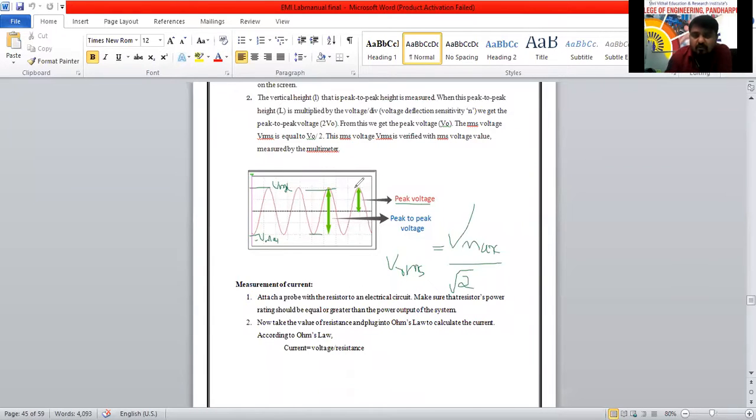That is the AC voltage it is going to give, and this is the peak to peak value we are going to measure here, and the peak value and the time period. Time period is very important. If we know the value of resistance, then the voltage we have measured, divided by 5 ohm, we are going to get the current value.